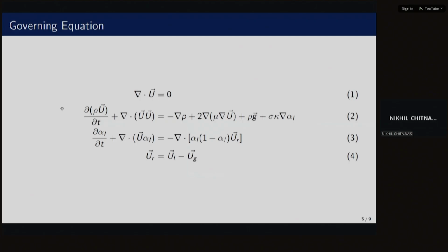Further moving forward, as I've already said, this is a VOF model, which is used for solving the multiphase flow. These are the governing equations which it is solving, starting with the continuity equation and the momentum equation. If you look at this momentum equation, one additional source term it is going to solve. As we are solving two different fluids, with one being the continuous fluid, which is water, surface tension will come into effect, and this surface tension force is treated as a source term in the momentum equation.